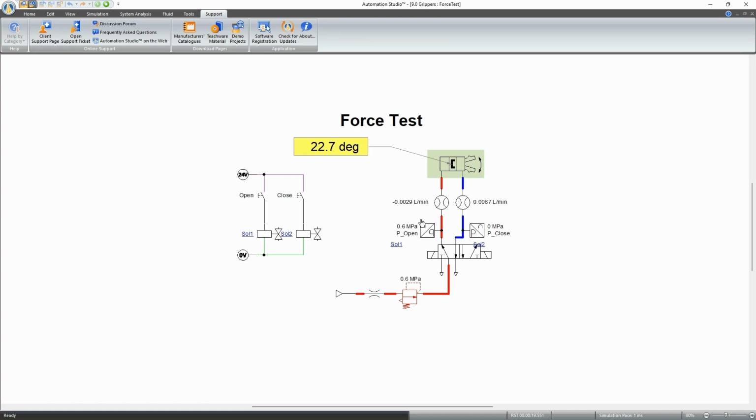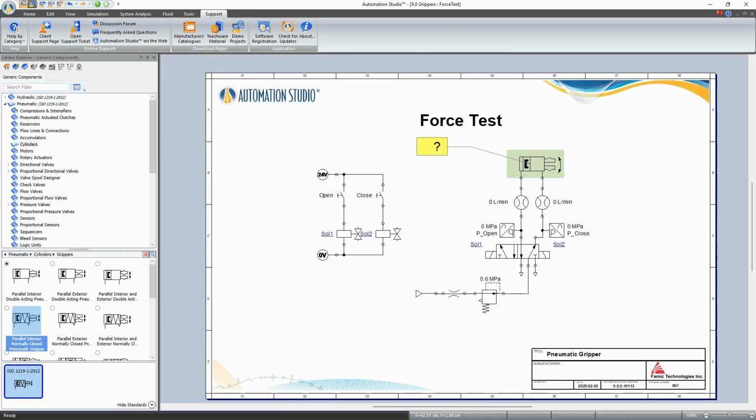So this will calculate, obviously, the amount of pressure required, the position versus the pressure, and how much flow is needed. So if you're doing repeated cycles, and the amount of gas that you're consuming is an important parameter, then it calculates correctly the amount of gas based on the information that's available in the specification. So that's basically it for the grippers.